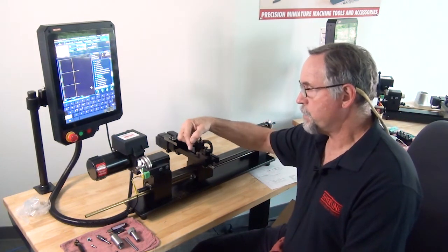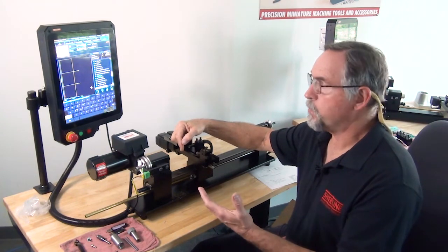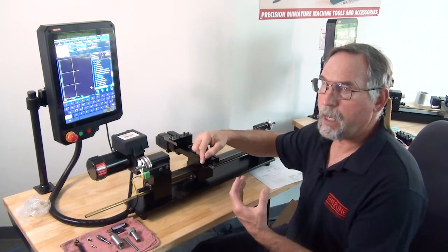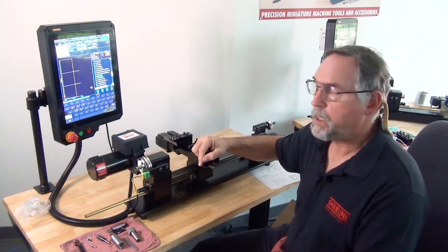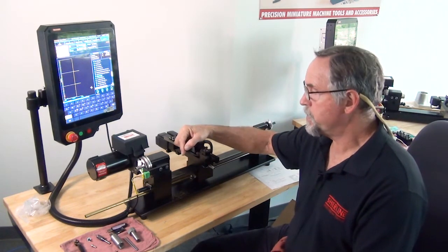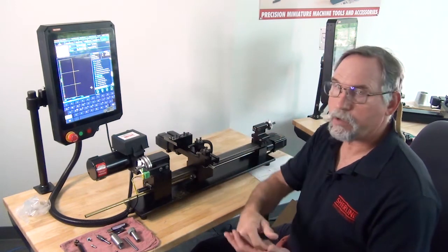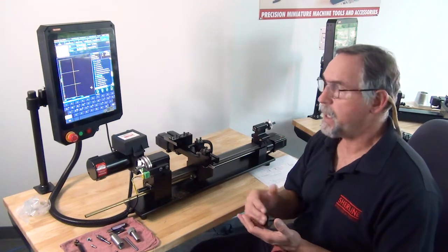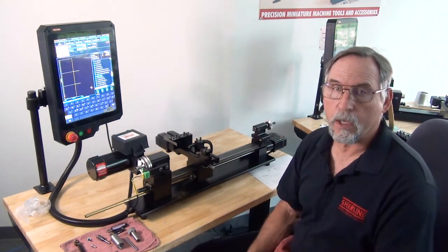And as it cuts towards the middle of the part to 0, the RPMs are going to pick up to 2800. As it feeds back out, the RPMs are going to drop down to much lower than that, in a 200 range. Then it's going to feed back into 1 inch and feed out. At 1 inch, whatever you calculated for your maximum spindle speed using that formula, that's what it should be at 1 inch, because that value divided by 1 is that value.